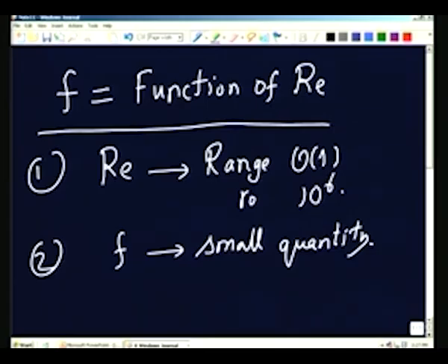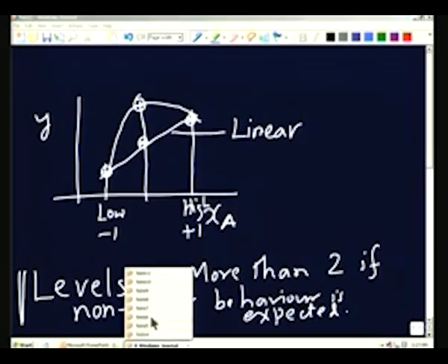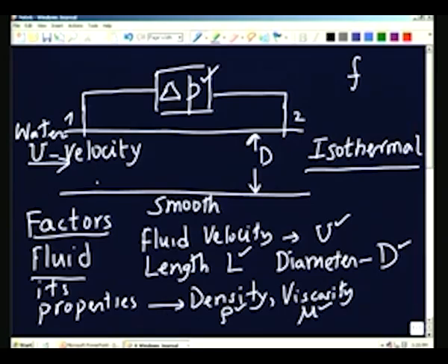Okay. So, if the range of the particular variable is very large, as in this case, it means that it may be difficult to cover the entire range by using a single fluid or single diameter and so on. So, that is where the experimental design has to concentrate. Let us just briefly explain that. I will go back to the first slide, where I introduced the idea of flow inside a tube. I will write here, Reynolds number definition is u d by nu.